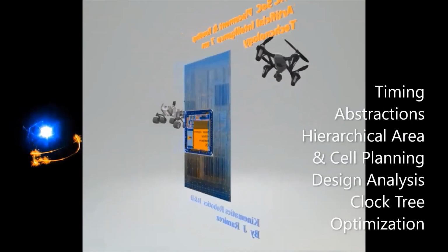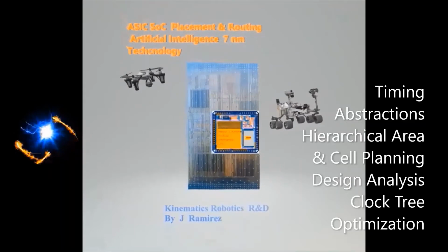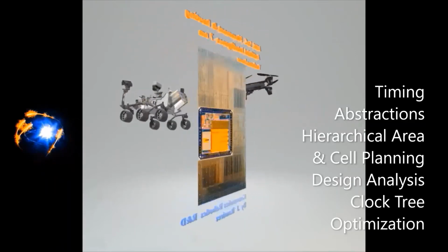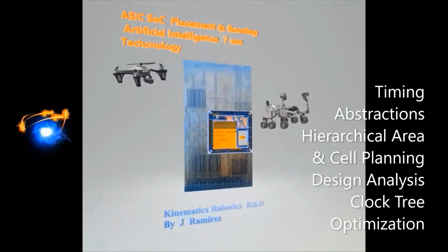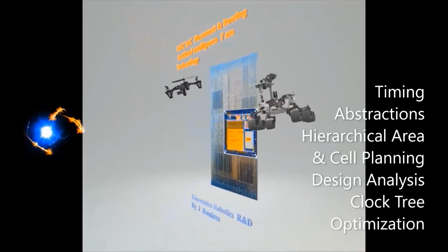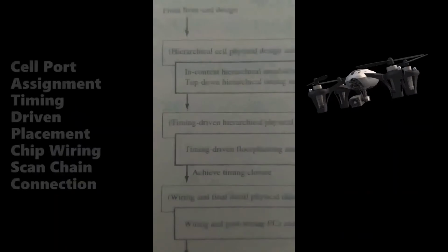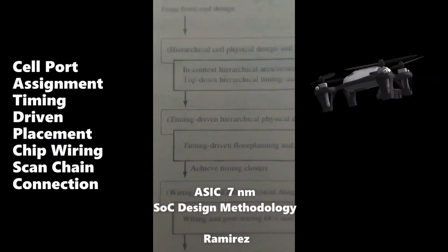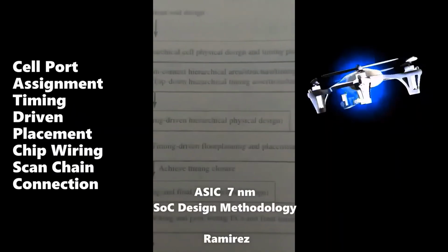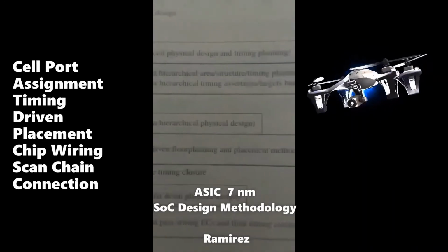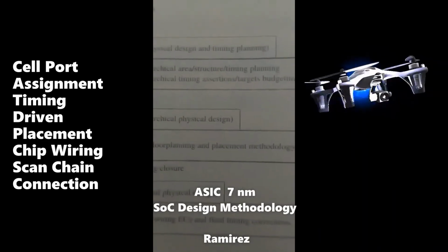Physical design methodology for the ASIC 7nm technology in the artificial intelligence system. First, identify connections to be optimized after placement so that they will not influence the placement. These include the scan and clock connections to latches.